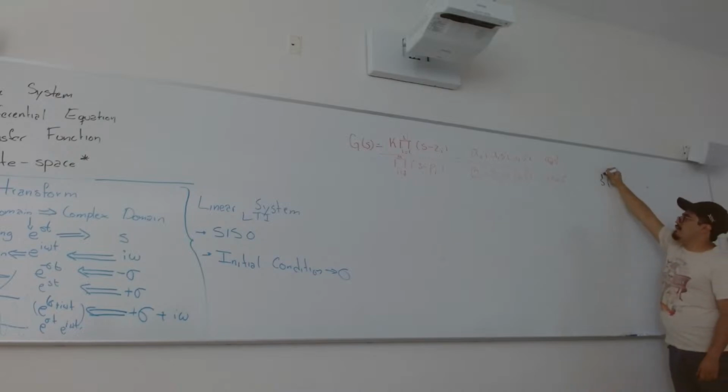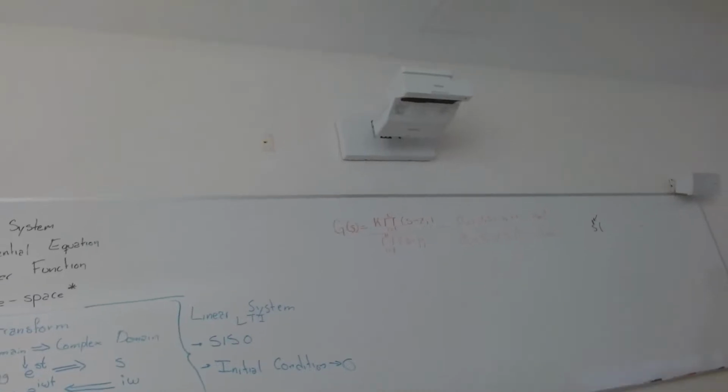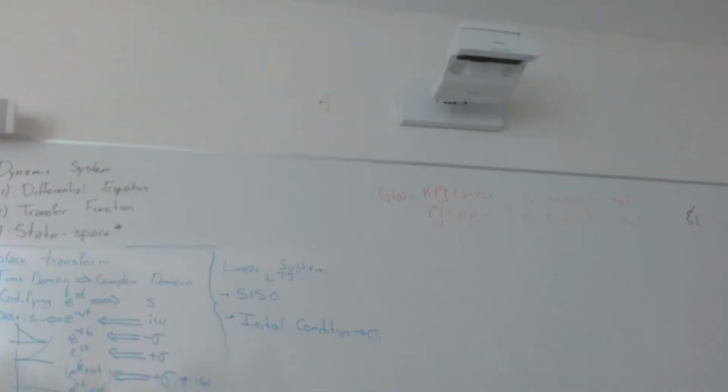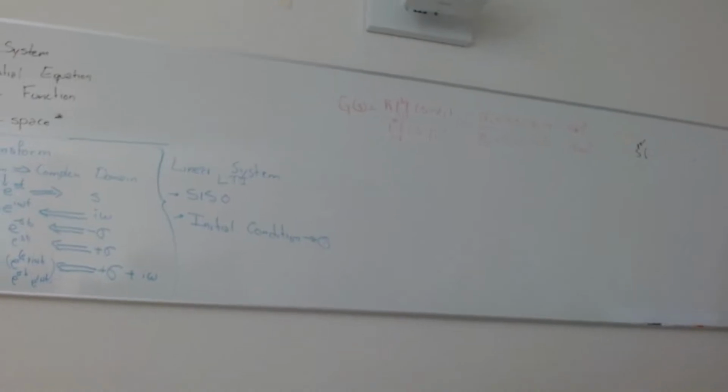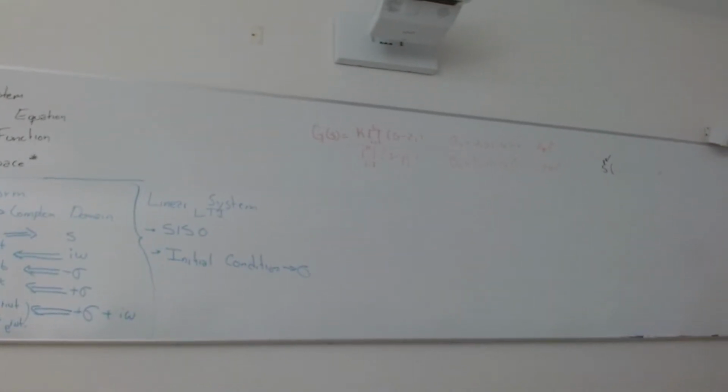And this helps you know what the steady-state values are going to be, because remember the integral part is important. It leads to a steady-state error of 0, and the more integrators you have in the system, you can achieve this error equal to 0 for more inputs than just the step.